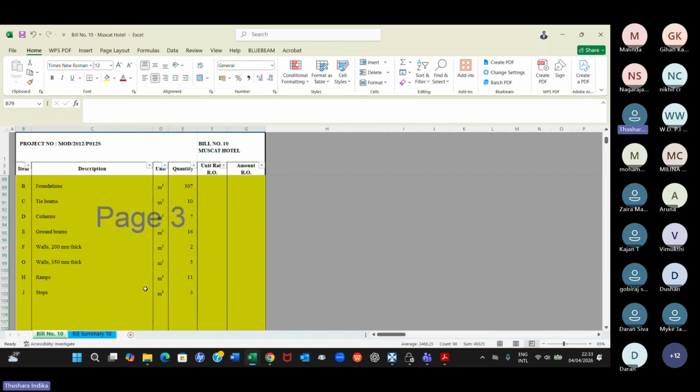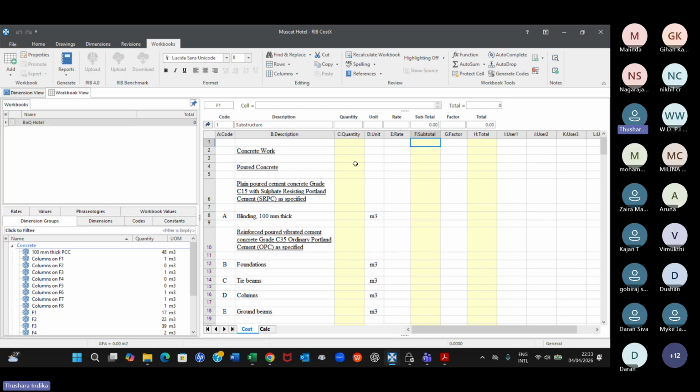Otherwise, you just copy everything like what I did and then remove the unnecessary quantity. You have to remove it anyway. And the unit, you have to move from this column to this column. Whatever way you copy and paste your Excel BOQ into this one, finish. You don't need the quantity, but you need the units. You can just type units if you want. The practical thing is, of course, nobody will type the BOQ from scratch. You will take a copy from the Excel sheet and paste it here.